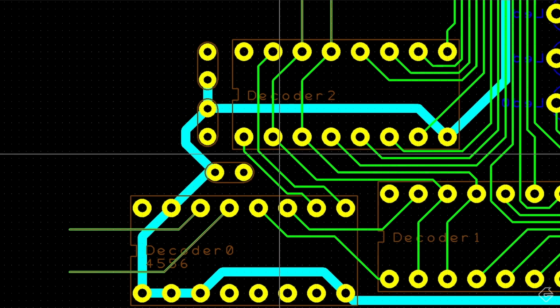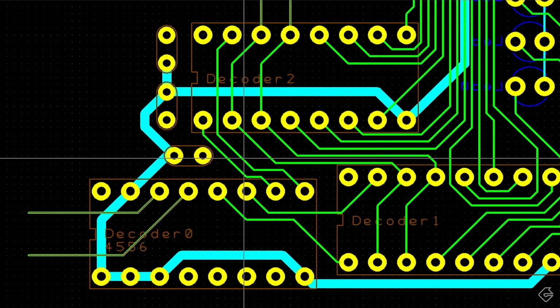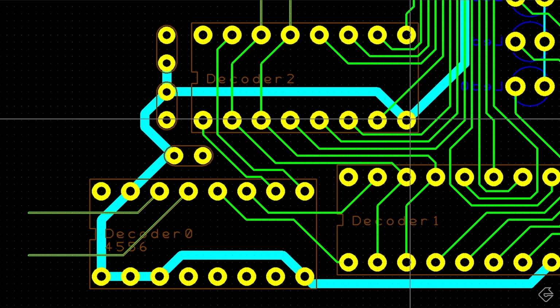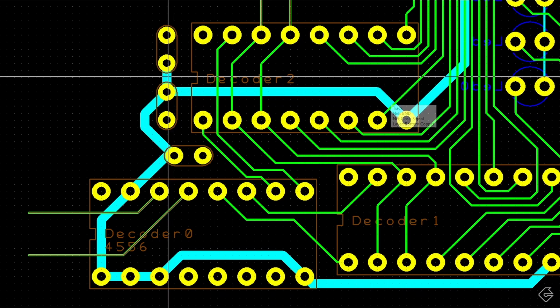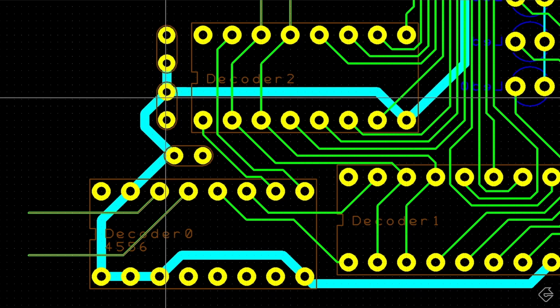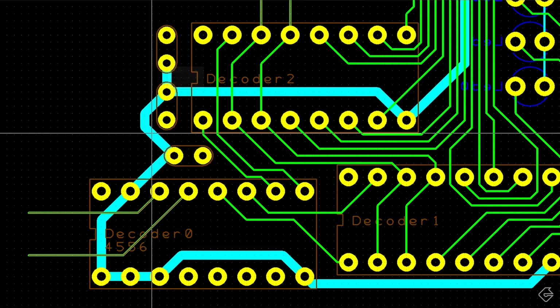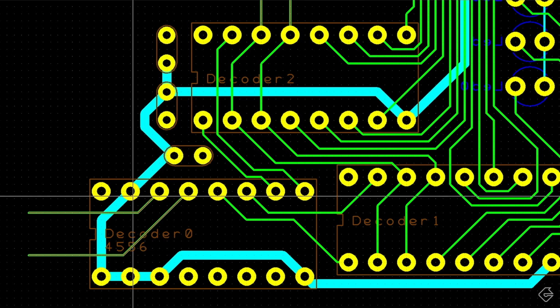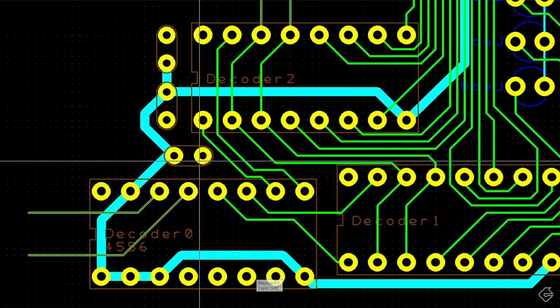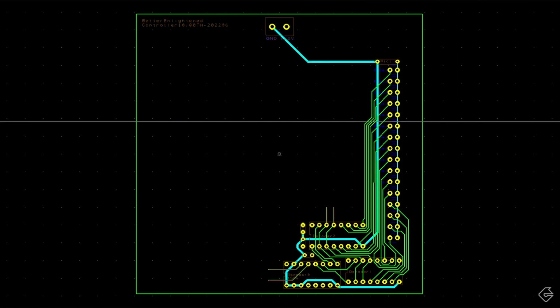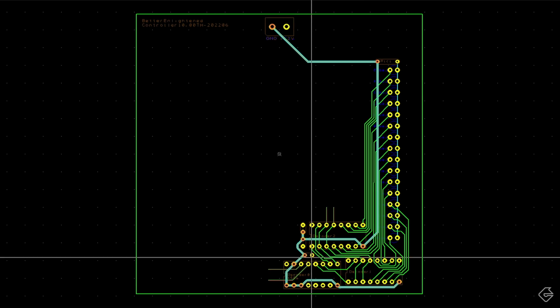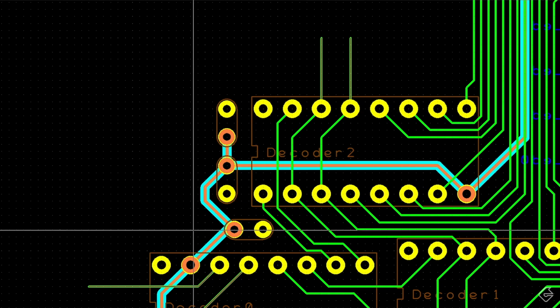Now that the capacitors are in place, I can attach the ground, which I had left alone. By putting the ground in place, I've now decided the polarity of these capacitors. So these are going to be the 2 ground pins for these 2 capacitors, and the ground goes onto this side, and then it continues on. So now my ground is fully connected. And if I zoom out and hit the ground layer, you'll see that it's a fully connected ground path going to all of the chips that are necessary. What's left now is to connect the other side of those capacitors.